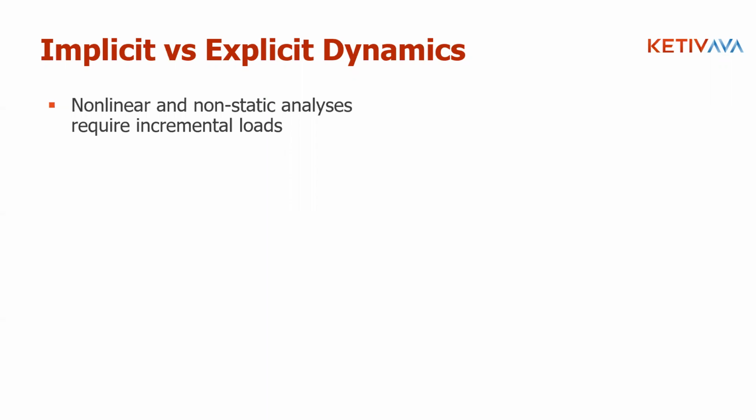It needs to be able to capture that so that it uses this new behavior, this new nonlinear behavior, for all the subsequent time steps going forward. And so it's important that we use incremental loads and not just one single load applied at one instant of time.